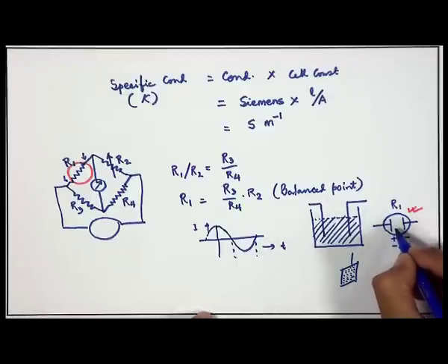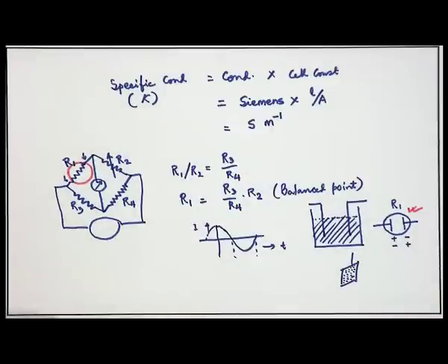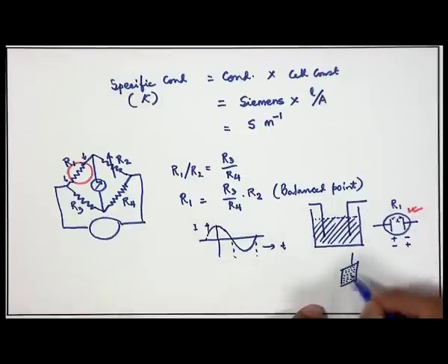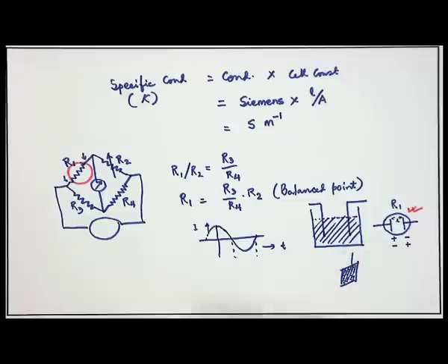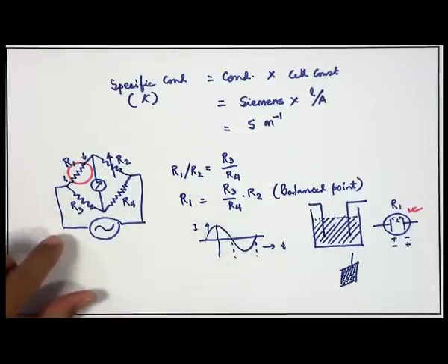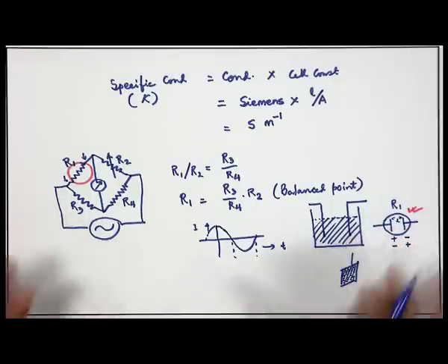across these two electrodes. So, basically you are putting this cell over here, that is why the cell constant is coming over here. So, cell constant is nothing but the ratio of the length between these two electrodes. This is your L, and this is your A, this is the area you are talking about. Okay. So, therefore, L by A is the cell constant. So, this way you make use of this AC supply to measure the resistance, I mean the conductance of the cell, that means conductance of the cell which is containing your required material.